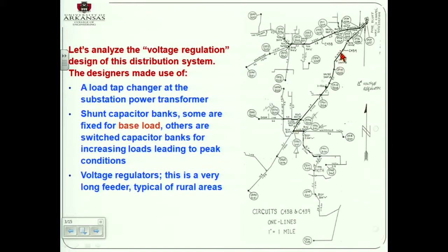And here they have one that is 300 kVAR, a fixed capacitor that I put there, and it's before the voltage regulator. Why? Because if you put it on the other side, every time that this gives you a step on the voltage, you are going to get some inrush current, right? The dV/dt is equal to I divided by C.